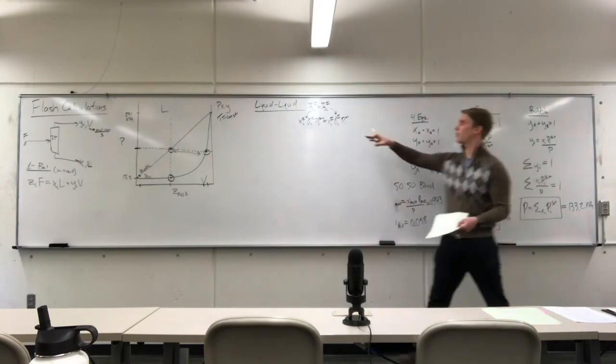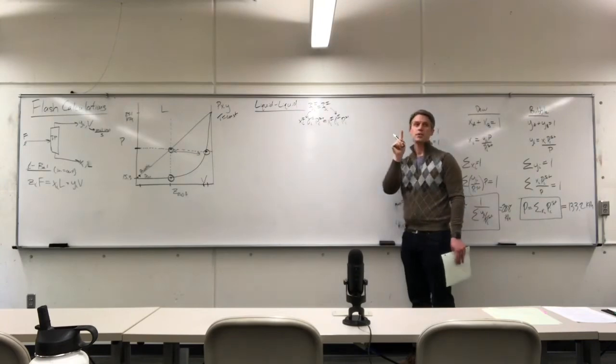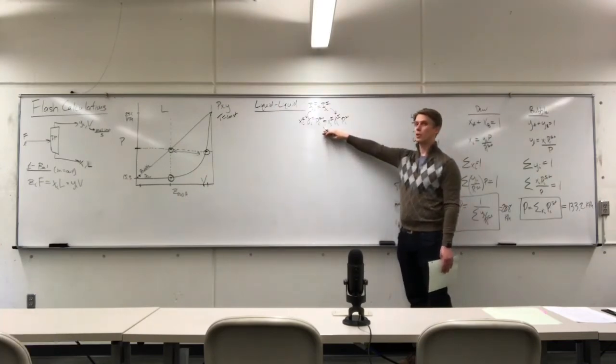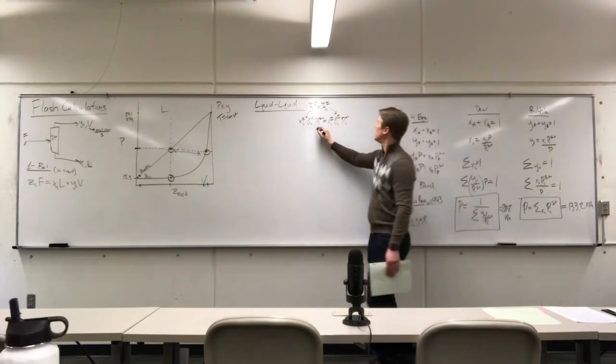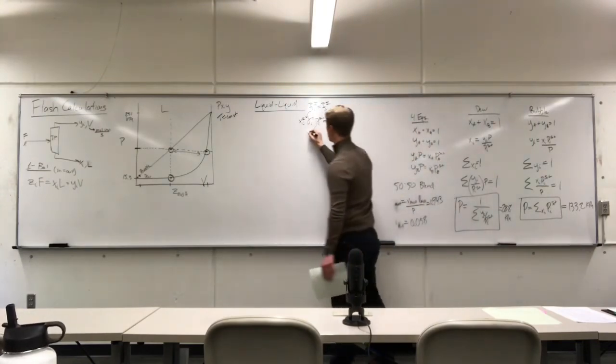Now, in this case, we've effectively assumed all the assumptions can be lumped into one, which is an ideal gas vapor, right? Or low pressure. So this is low pressure liquid-liquid equilibrium. The pure fluid saturations cancel out.